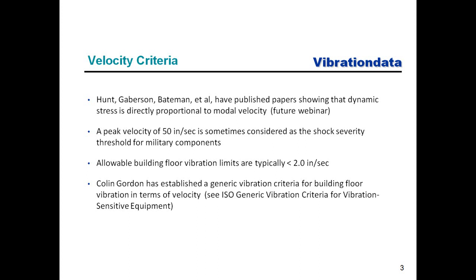And these engineers have come up with a kind of a rule of thumb stating that a peak velocity of 50 inches per second is sometimes considered as the shock severity threshold for military components. So if a military component will be subjected to a shock that has a pseudo velocity of less than 50 inches per second, then shock testing may not be required or may be optional.